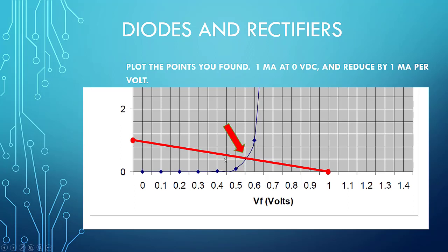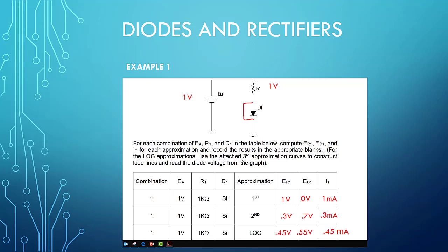And if I bring that back, this was 0.4, this is 0.8, this is 1. So if this is 0.55, maybe I'm up to about 0.45 milliamps. Probably would have said not quite 0.45 on the milliamps, but at any rate, if I follow my graph, my diode is 0.55 volts. That leaves the rest of the 1 volt for my resistor, and then my milliamps accordingly.